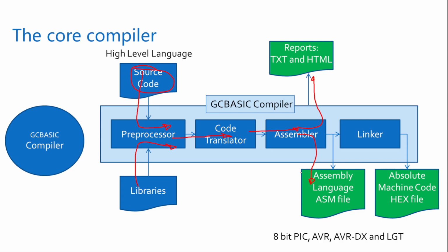Then within the core compiler, it will link that together and produce a hex file. In the linker, it works out where to put your assembly in the hex file. So it works out the memory for that particular chip and puts it out. At this point, you get a file that you can program. That is the core compiler. That is as it was in 2005, and has not changed. Let's be quite frank, there's a lot more richness going on, but that is the basic architecture.